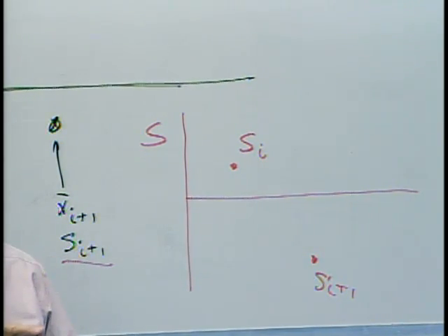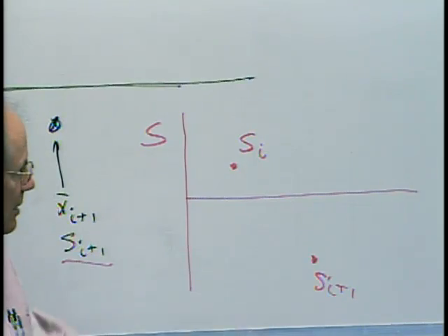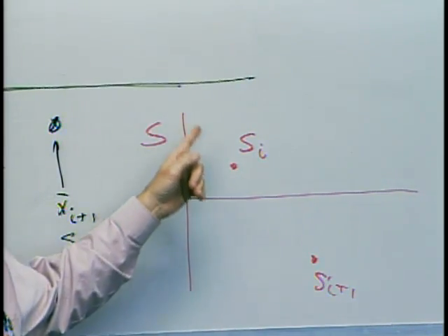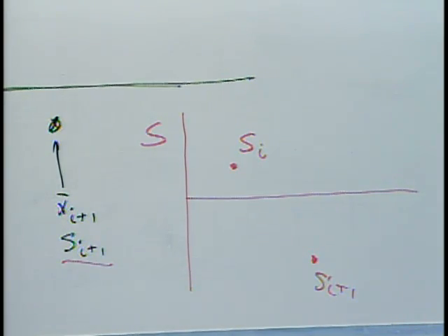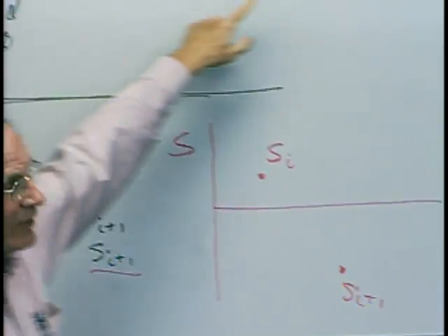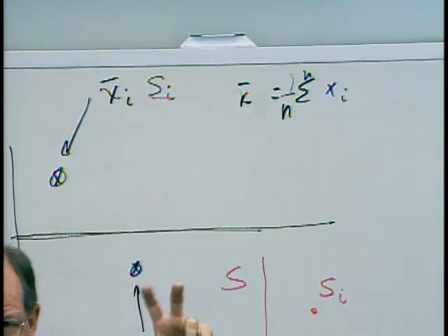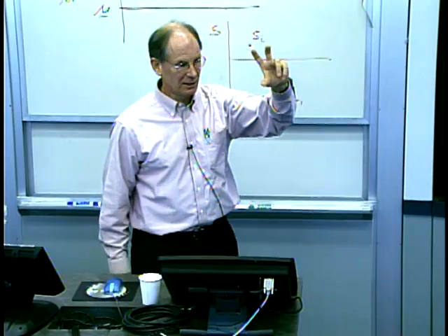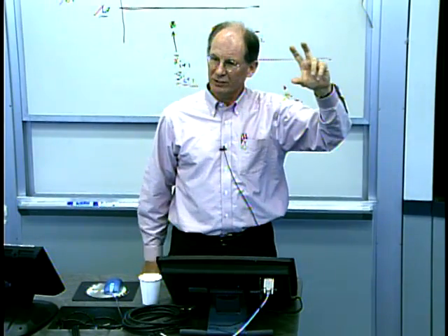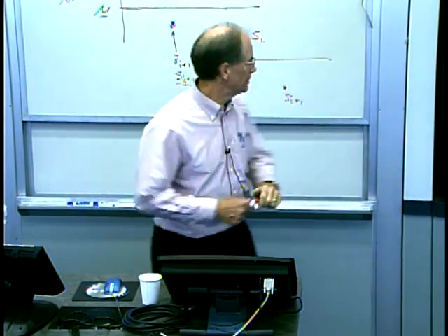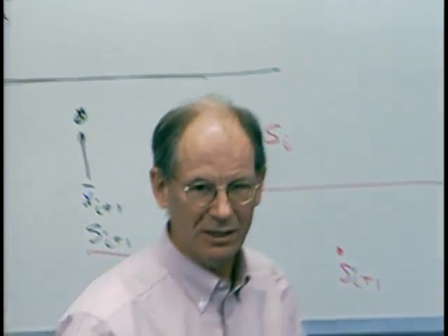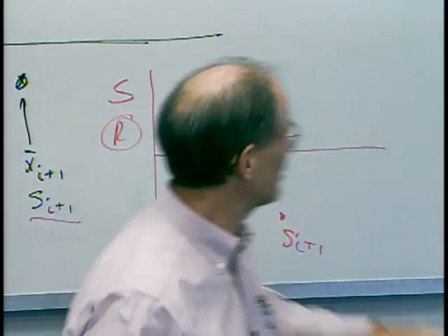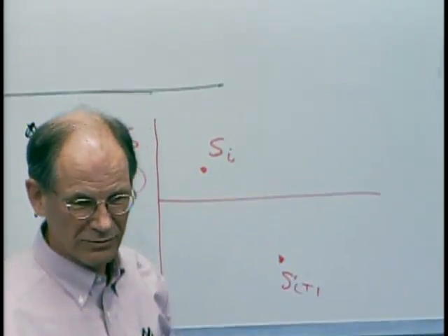Now in most texts on this, I know Montgomery talks about S charts. He also talks a lot about R charts. The R chart basically says, for this sample of n data, what's the min-max range of it? Why do you think we used range for so many years, and a lot of the literature is on R, especially if n is like 5?